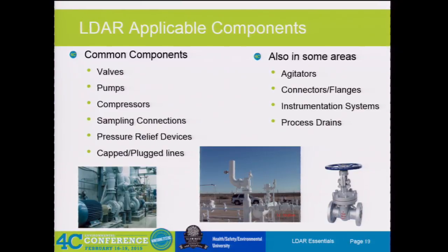Now, most folks, I've had many arguments, or heavily discussed, let's put it that way, where they say it's a double block because you can always backtrace upstream and find that next valve. But if you can prove to me that your operator went from here and then walked 60 feet over and climbed a deck and then went over and closed this valve and did it right and purged that system, your operator's a hell of a lot better than a lot of folks I've seen.